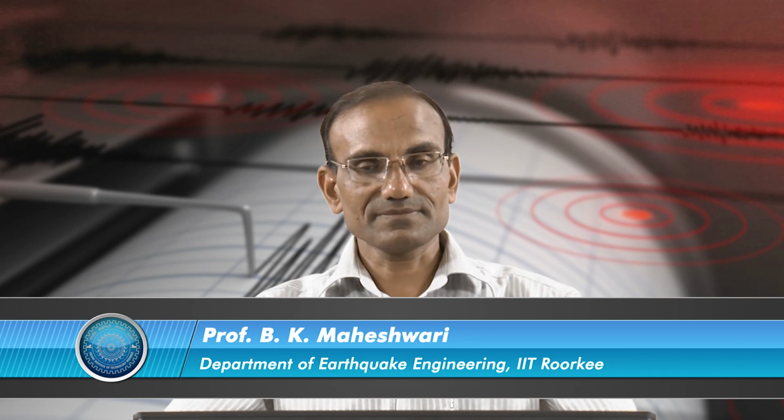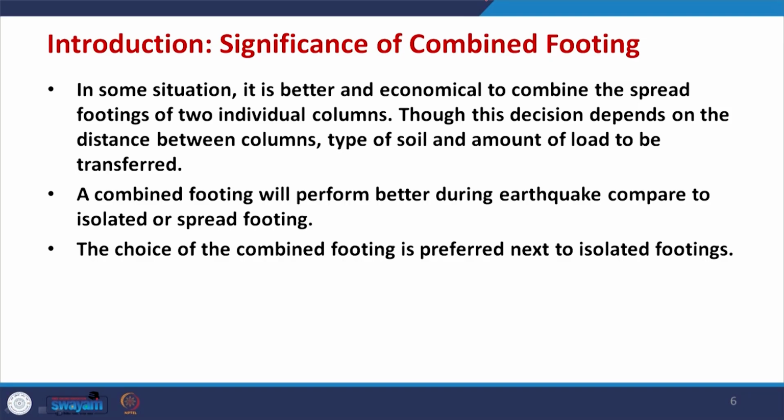When we talk about combined footings, you may be aware that there are situations where it is better or rather economical to combine the spread footings of two individual columns, though this decision depends on the amount of the load coming, type of soil and situation, and the distance between the two columns.